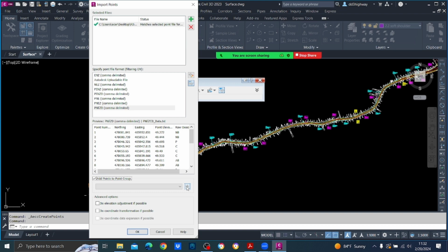So what we do is import the points part by part. Say from 0 to 5, 5 to 10, 10 to 15, like that. After that, just think that you want to delete all the data from kilometers 5 to 10. Then can you do that? If you put everything into the all files and jumbled it, then you can't delete it. But if you imported everything from 0 to 5, 5 to 10, 10 to 15 like that, and you want to delete 5 to 10, you can select that point group and delete it. That is why you are going to create a point group here.